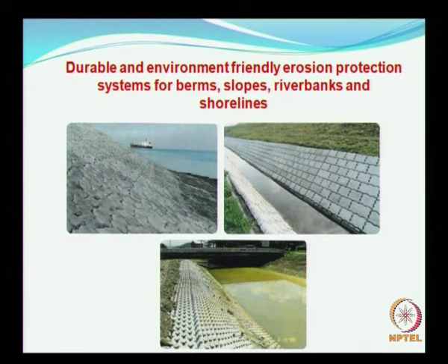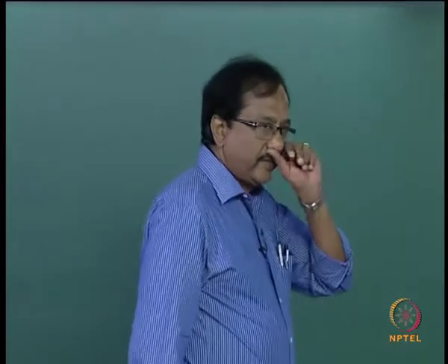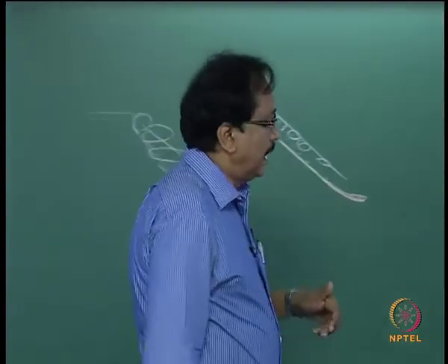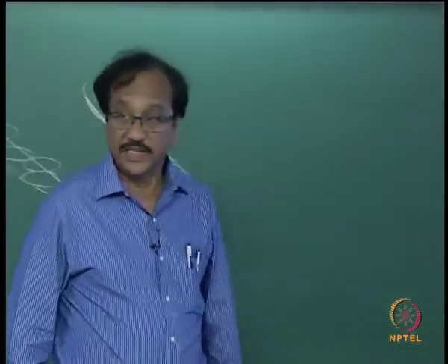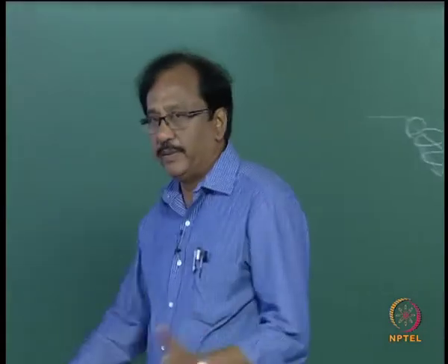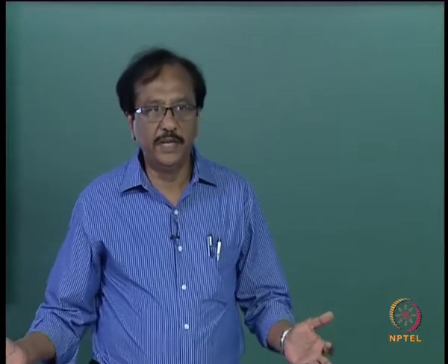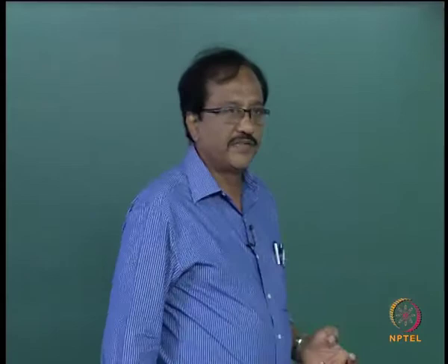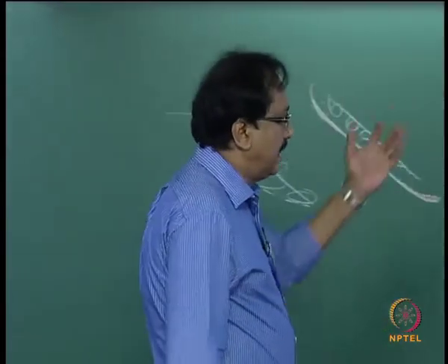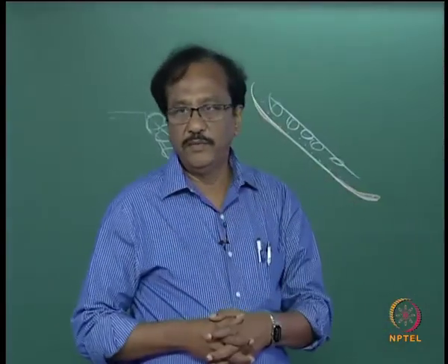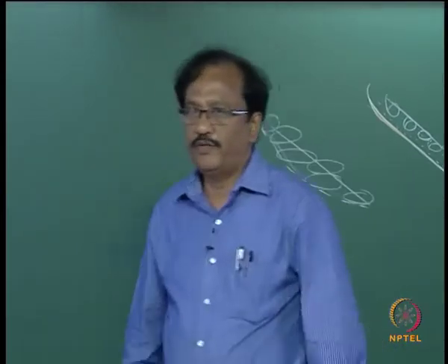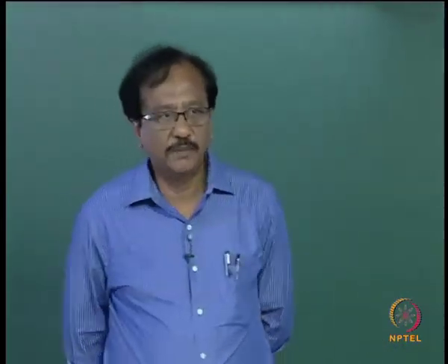So we have a variety of choices, but you have to be careful in choosing, and you have a cost benefit aspect which you need to consider. Some of these things also require skilled labour. For example, placing rubble stones, you may not require skilled labour, but using this you need some kind of special machinery and special skilled labour. All these things have to be taken into account when you are planning your structures. Is that clear?